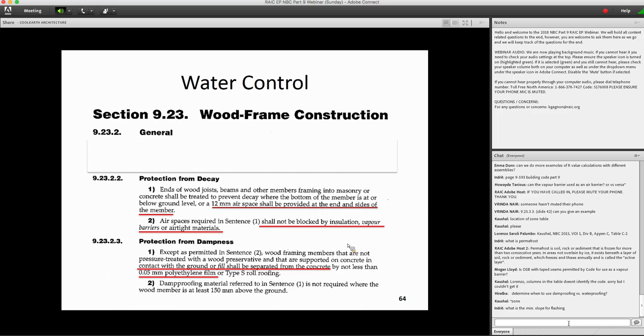If you have a concrete base and you have a wood column or a wood beam touching directly into that, you might have some water flowing through the pores of that concrete, and it will penetrate into the wood, will rot, and will decay. So you do need to separate those two components with a polyethylene film.